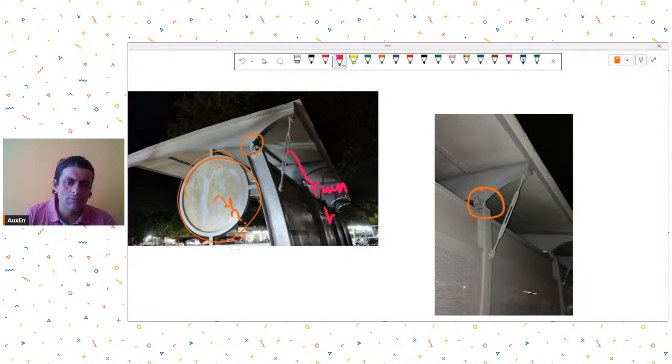So this turnbuckle arrangement is to pre-tension this anchor. So this has been kept under pre-tensioning, so that if this system tries to rotate like this in the gravity direction, this will pull it down through tension force. But what about the load reversal? If there was a load reversal that was to happen, then this system will come under compression. This turnbuckle will come under compression. Under compression, it will not be stable.